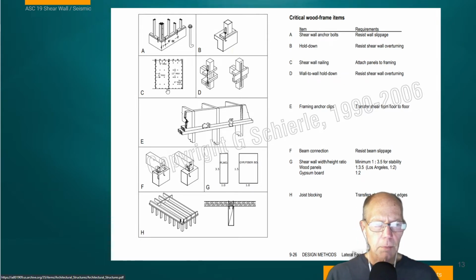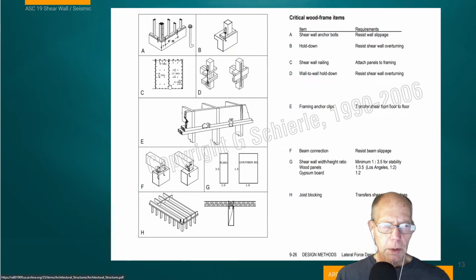C is the panel nailing scheme. And this is really critical and something that building inspectors would catch, and something that an architect who might be doing a site visit should be well attuned to also. This is the plywood sheathing on the wall, and this would be a nailing schedule. So we have this idea of spacing the nailing. Typically the code specifies 6 inches max along the perimeter. And then they have a term they call in the field, where sometimes that spacing is relaxed to like 12 inches.